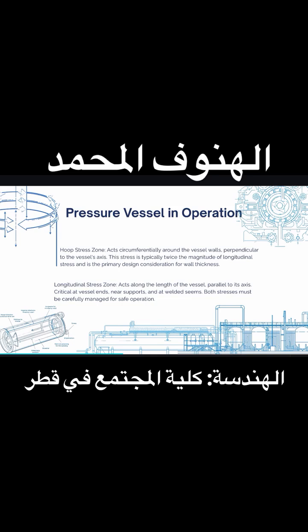Pressure vessel stresses. Hoop stress acts circumferentially around the vessel wall, perpendicular to the vessel's axis. This stress is typically twice the magnitude of longitudinal stress, and it is the primary consideration in determining wall thickness.